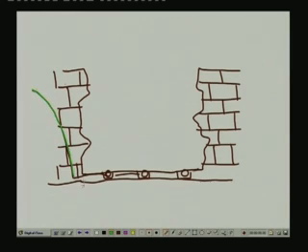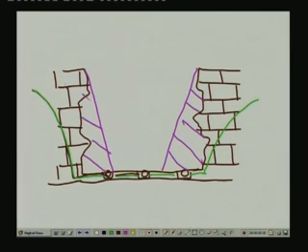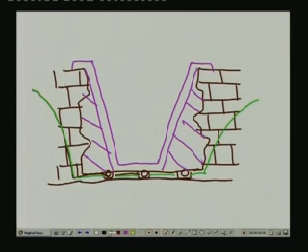So let's say the groundwater table in this particular case is going to be drawn down like this, and then inside the excavation a backfill was placed like this, and inside the backfill was constructed a clay liner, and on top of the clay liner there was a geosynthetic membrane, geomembrane actually, impermeable geomembrane,